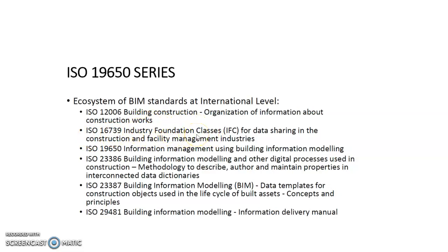Remember I talked about the fact that some of the design software, the input and output file extension, cannot be read by other design software. So you need to convert it into a .ifc format. IFC stands for Industry Foundation Classes, so that the data can be used by the different software that don't talk to each other.